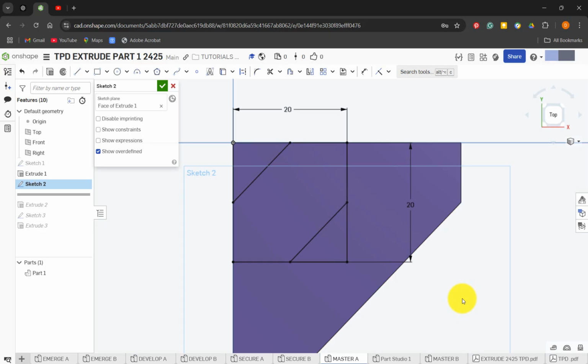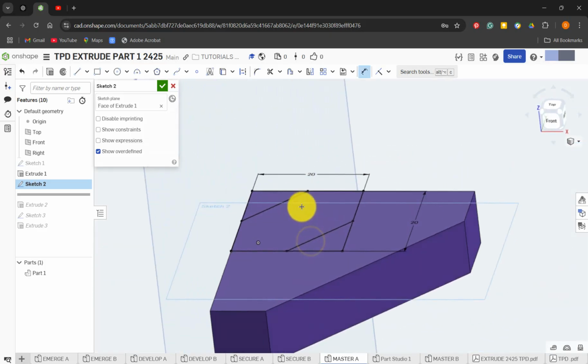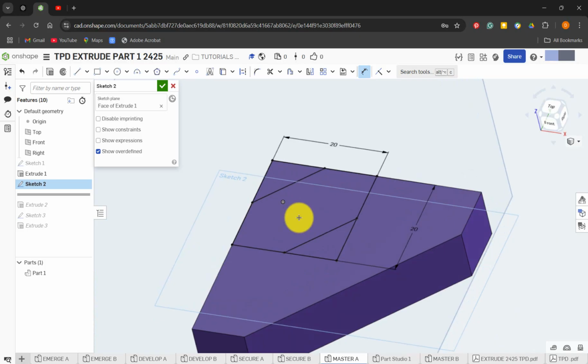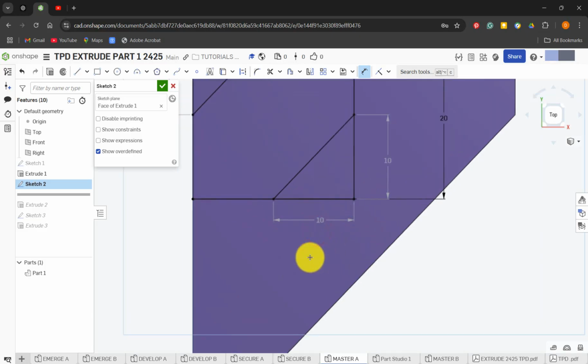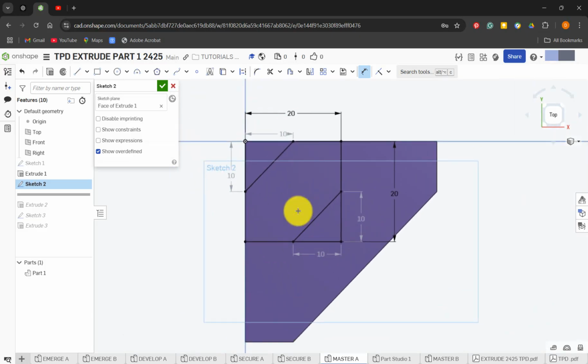So if I wanted to put some extra dimensions in there, and if we have a look at that angle, yeah, so press N, I can click on here and you'll see that these are dimensioned to be 10 each one of those particular points there, like so. So fairly simple, a repeat of what we've done previously, but it's obviously a bit smaller.